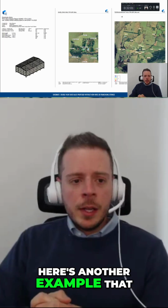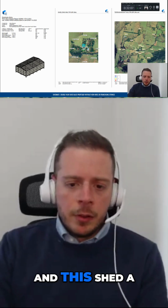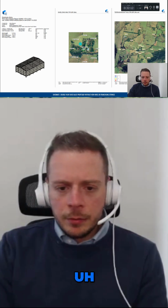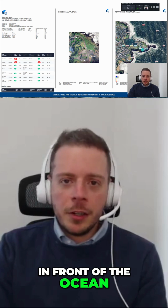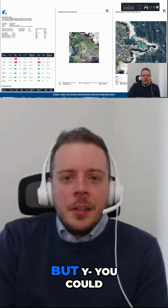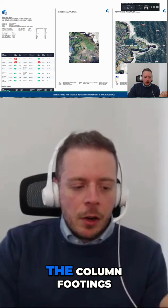Here's another example where I've done a very similar study. This now is in New South Wales, and this shed A is in the middle of lots of trees. It's kind of a farm area, and shed B is in front of the ocean again. Obviously, I'm exaggerating a little bit in this demonstration, but you could build a shed there, right? And as you can see, this example doesn't pass for the columns, for the rafters, and the column footings.